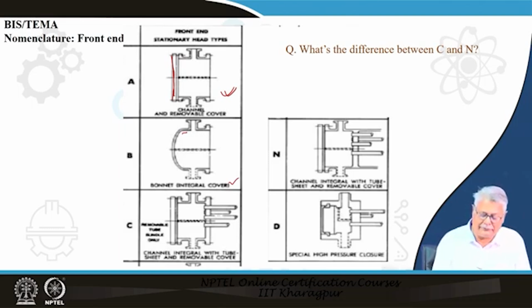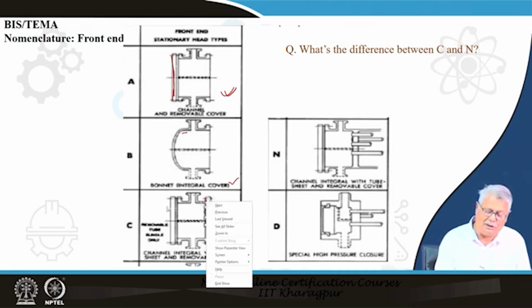In this case, the channel is integral with the tube sheet. You will notice this is your tube sheet in which the tubes come and end. So, you have this channel integral. This and this are built together and you have an external removable cover.